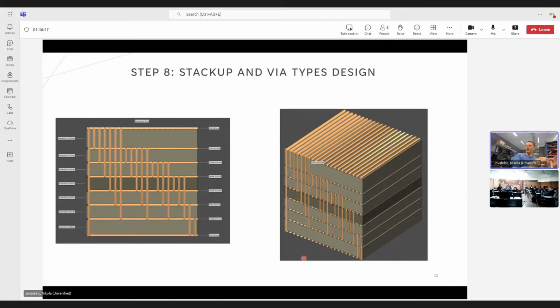What you need to remember here is you need to simulate to see if you will have signal integrity problems. So your amplitude of the signal will be decreased. If you have a link or interconnect which is 1 centimeter, or you have a very big PCB which is 60 centimeters, it needs to trigger your alarm immediately when you see such big distances and you have a high speed signal. You need to simulate and to see what's going on. Otherwise, you will make a mistake.